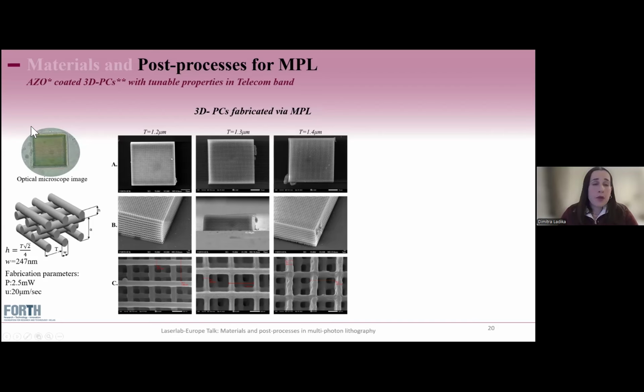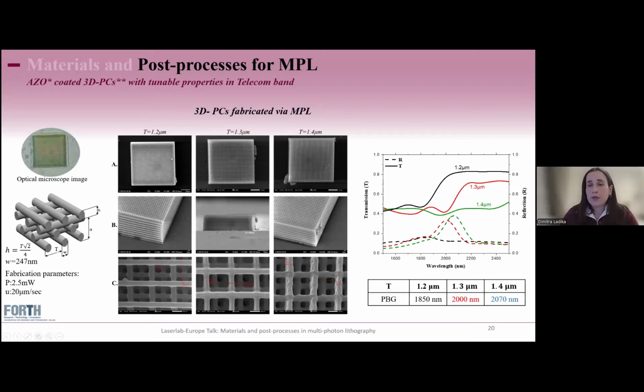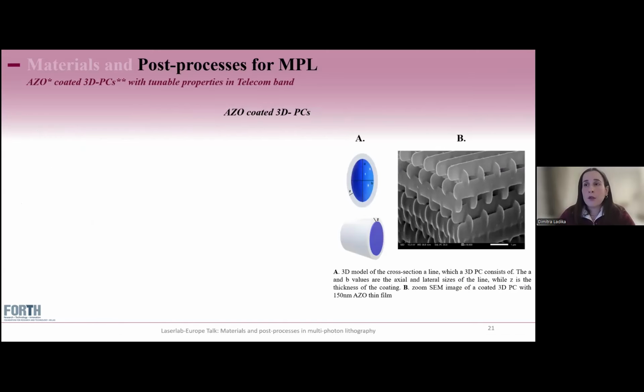So probably we have a photonic band gap, and we are not speaking only of a bulky cube. And indeed, from the FTIR measurements, we see that all our photonic crystals show a band gap, 3 different band gaps actually, in the area that we're expecting according to previous publications and some simulations we have conducted.